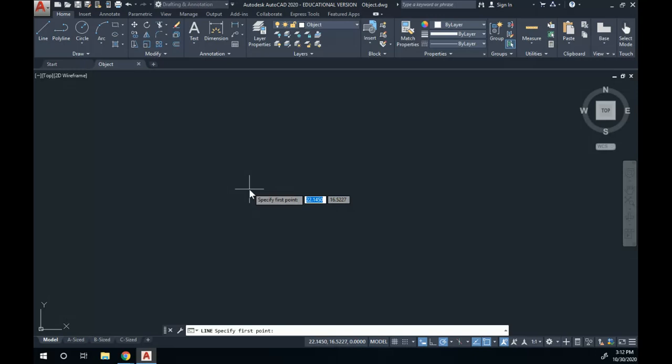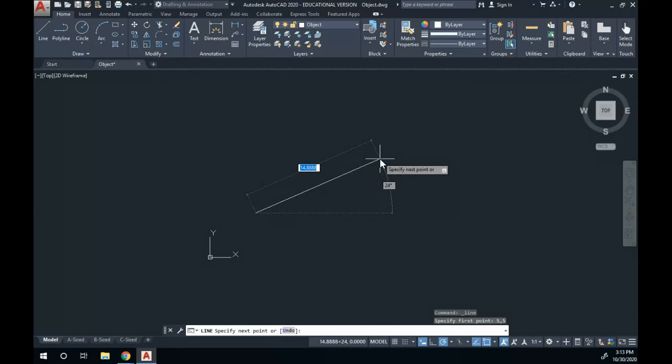The first highlighted blue number is the X coordinate. I can manually type that in, hit 5. To move over to the next point, I can hit the tab key. Tab will move me over to the next number. I'll hit 5 again, and once I do that, I'll press enter. It specifies the exact point. If I look at my Cartesian point, here's the origin. I come over 5 and up 5, and that's where the beginning of my line is placed.